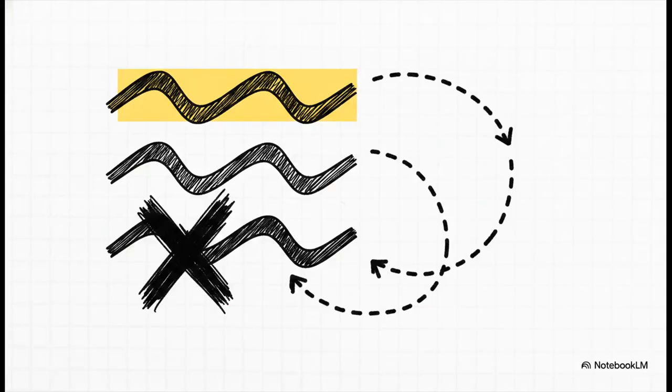It's pretty amazing, right? This brilliantly illustrates how an intimidating, multivariable 3-phase problem collapses into a super basic single-phase calculation. You literally throw away 2/3 of your circuit, solve one phase, and shift 120 degrees twice to get the rest for free. They have the exact same magnitude, just different angles. This is arguably the single biggest simplification in power systems engineering, and it's for sure why absolutely every textbook and computer load flow program out there utilizes this exact per-phase method.